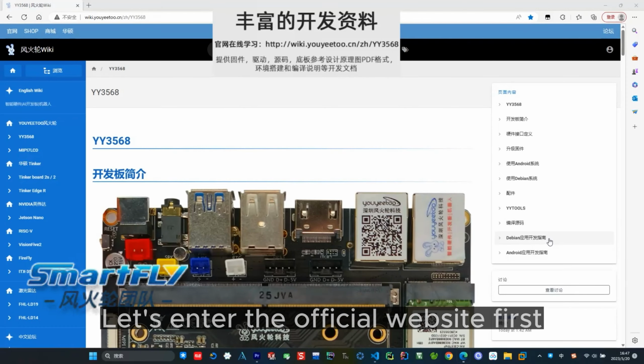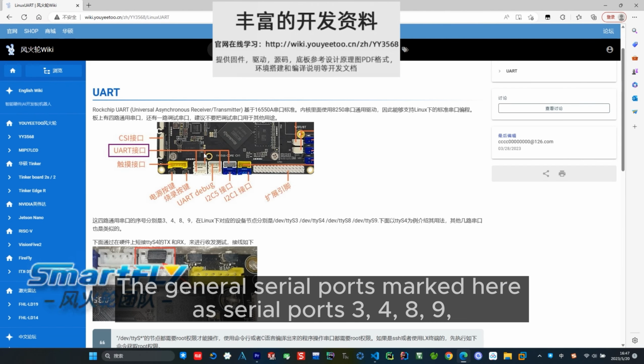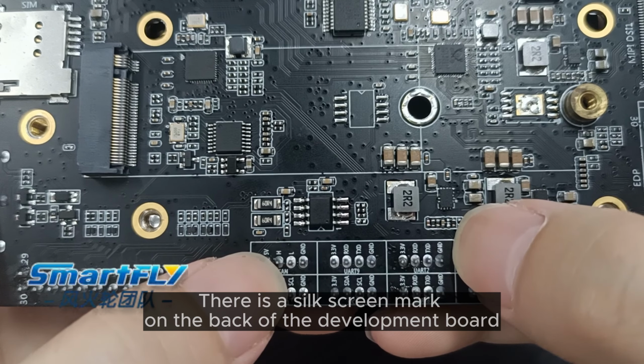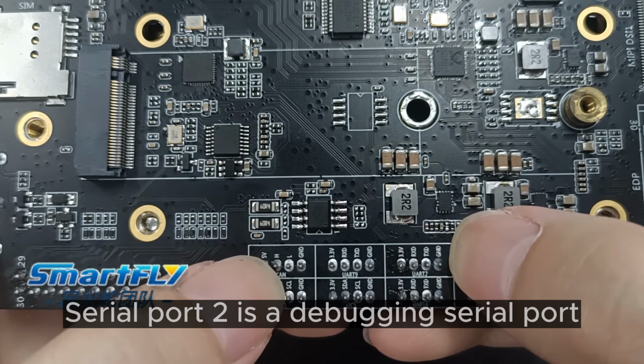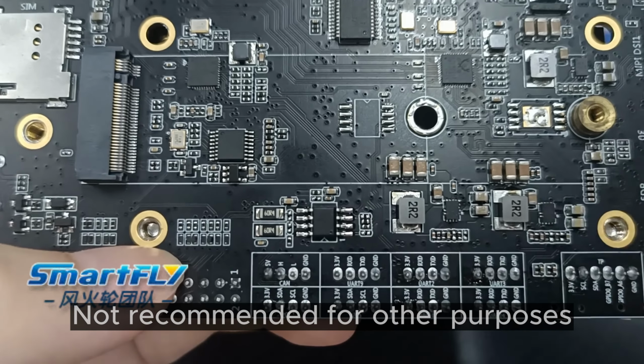Let's enter the official website first. Open the introduction about the serial port. The general serial ports are marked here as serial ports 3, 4, 8, 9. There is a silk screen mark on the back of the development board. Serial port 2 is a debugging serial port, not recommended for other purposes.